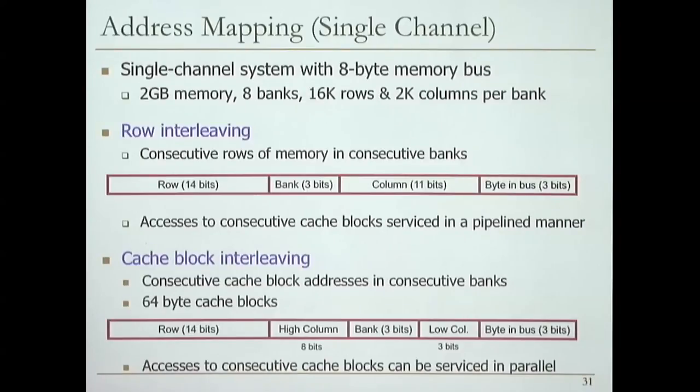So, even if you do one bank, it's actually pipelined today. Oh, because of the row buffer? Right, exactly, because of the row hit latency and the data burst. OK. Because of the page mode DRAM that we talked about last time. OK, thanks. So you can parallelize if you actually put it in different channels.